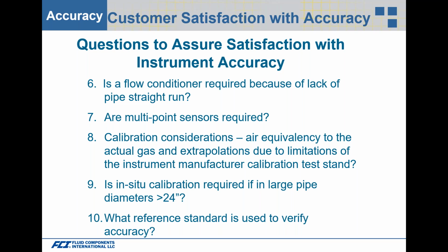And then calibration considerations. Is it air equivalency to the actual gas and extrapolations due to limitations of the calibration test stand? Many manufacturers only do air calibrations and they'll do an equivalency based on that. And then extrapolations. Some calibration test labs have limitations on what the minimum flow is and what the maximum flow is.